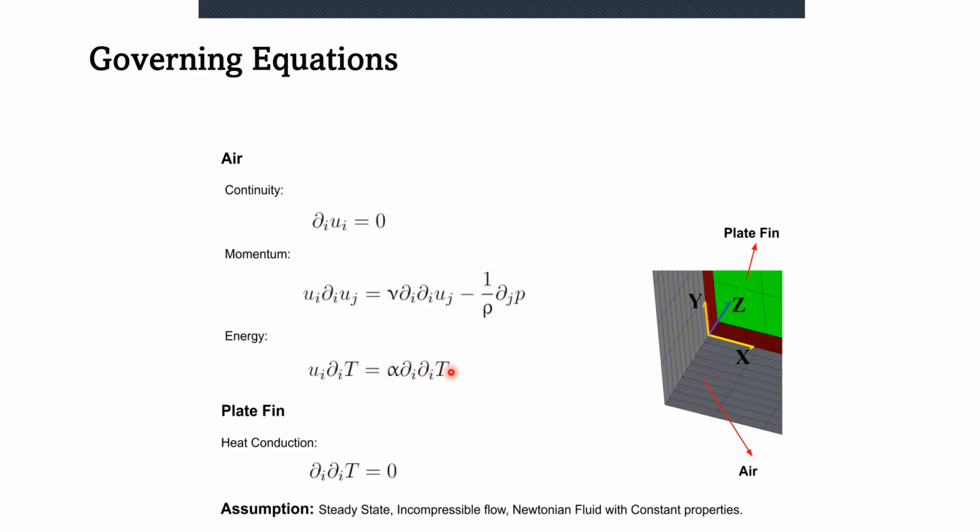In the energy equation, we have dropped the viscous dissipation term, considering the flow field is laminar. For the plate fin, the heat conduction equation is the Laplacian of temperature equal to 0, and we have considered no internal heat generation.